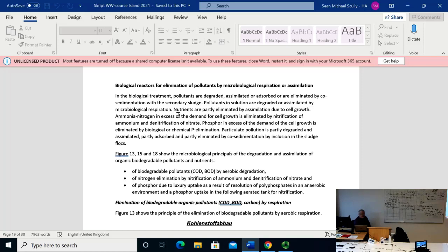In the cell mass, you have a COD to organic mass relation of 1.6. So the organic mass from the 100 grams of COD will be 50 divided by 1.6, which is 31.25 grams you will have in your hand as bacterial mass.